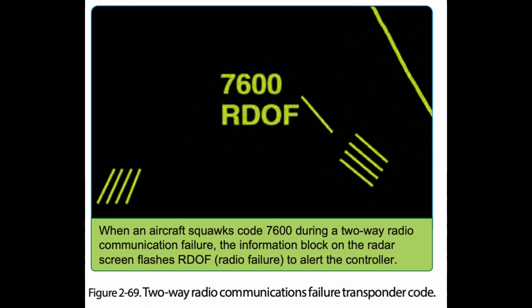If the radio fails while operating on an IFR clearance, but in VFR conditions, or if encountering VFR conditions at any time after the failure, continue the flight under VFR conditions if possible, and land as soon as practicable. The requirement to land as soon as practicable should not be construed to mean as soon as possible. Pilots retain the prerogative of exercising their best judgment and are not required to land at an unauthorized airport, at an airport unsuitable for the type of aircraft flown, or to land only minutes short of their intended destination.